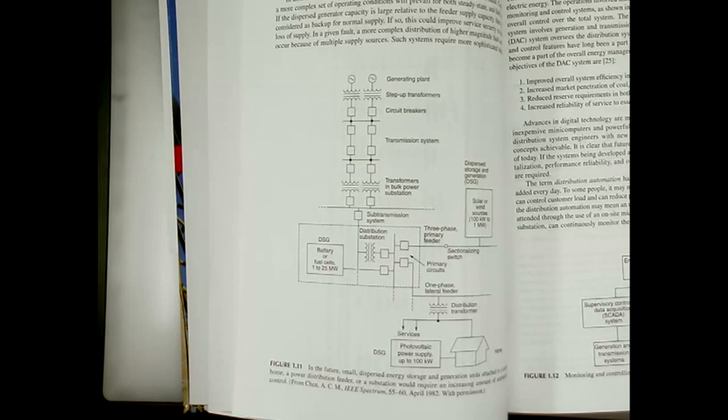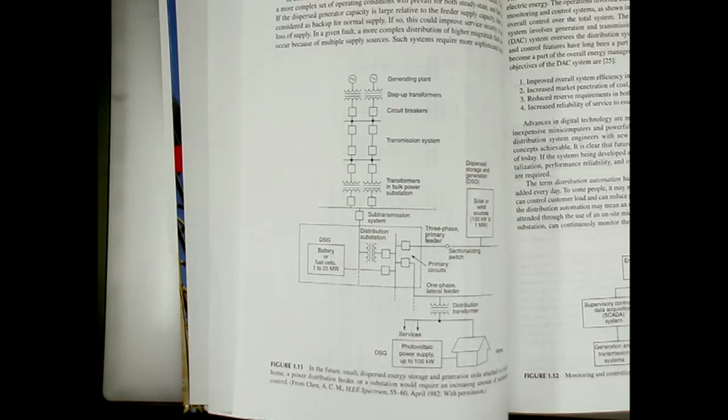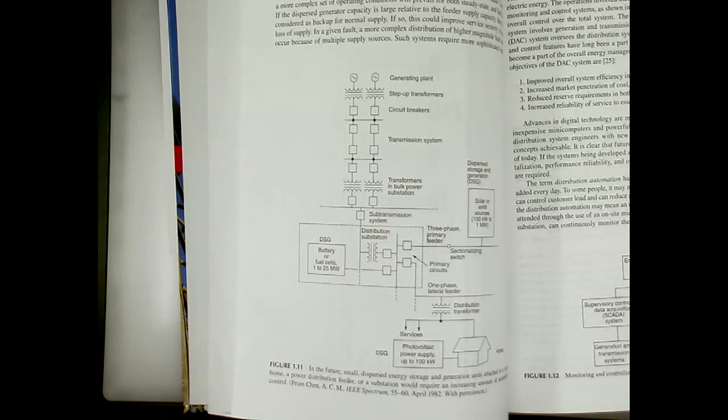So normally what they do is they step up from 480 volt to 13.8 kV or 12.47 or whatever, because there are a lot of manufacturers in that field. And then they're going to have a transformer that will go from 12.47 or 13.8 to whatever is your sub-transmission, 132 kV or 161 kV. So you don't use one step of transformation. You use two at least.